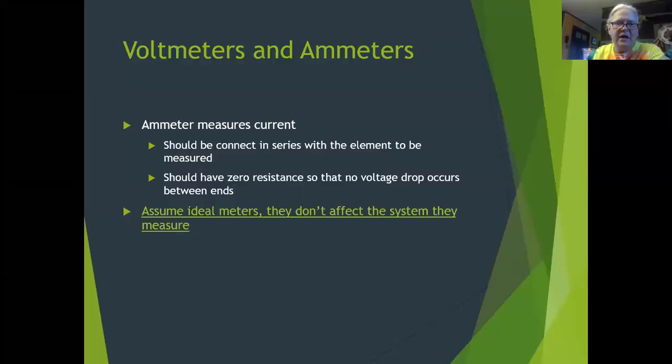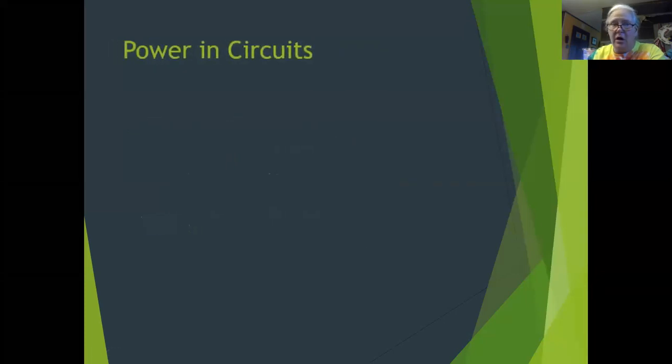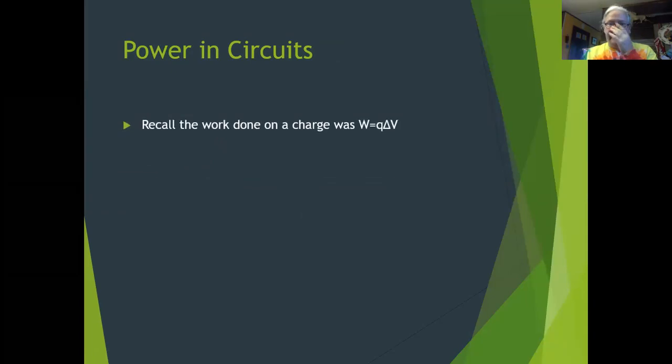Okay, so when we talk about these meters, we're going to be measuring different things in these circuits, and we talked about Ohm's law already. So we can measure voltage, we can measure resistance, we can measure current flow, but also we can measure power in a circuit. When you look at the power in a resistive circuit, there are different ways to calculate it.